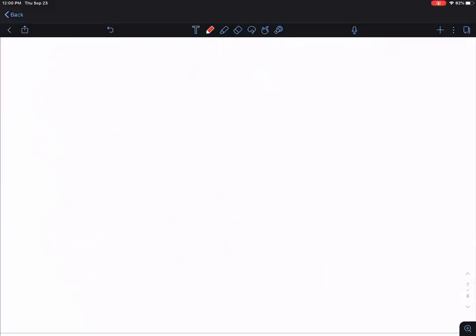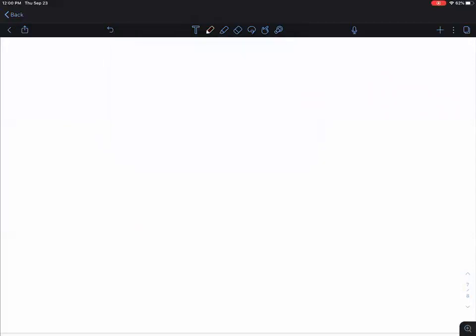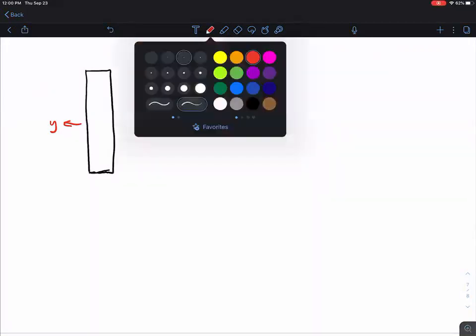Now let's look at the case where we're still considering the sign convention for bending moments, but now we'll look at the case where we have a vertical element. And so one question becomes, which direction does the local y-axis point? Well, in this case, we're going to show the positive local y-axis to the left. And this is fairly typical in a lot of structural analysis software.